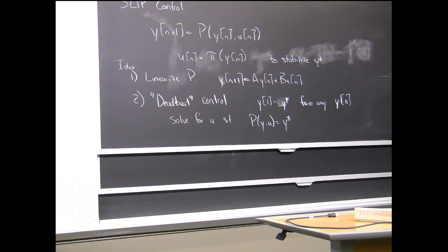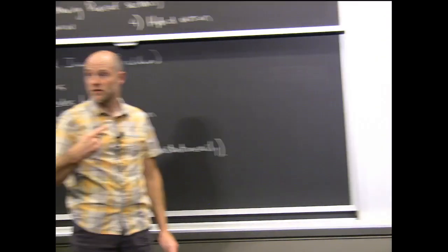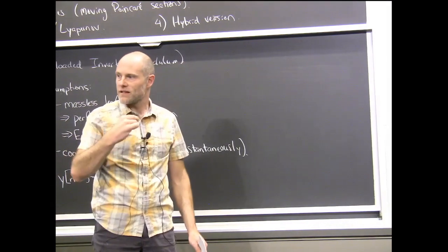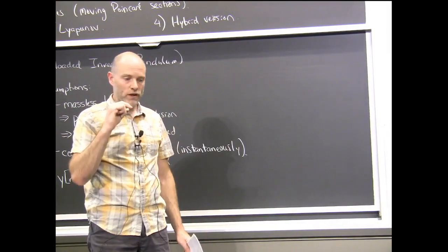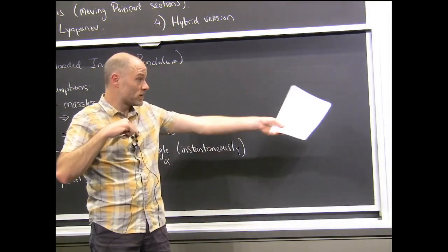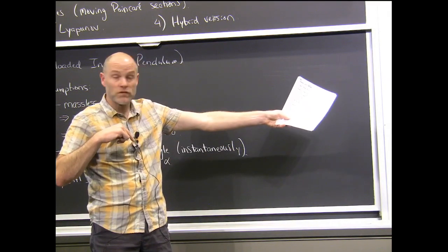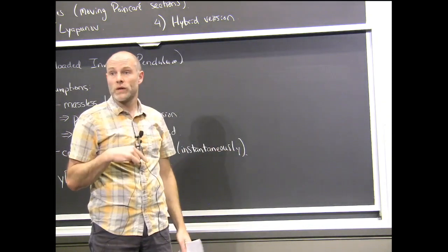Okay, so what does that mean? I'm hopping along, and I want to get to a new hopping height. I can choose a leg angle so that in exactly one step, I'm going to be at the new hopping height. That's a unique thing that we can do because we've gone to the discrete abstraction. We have time over the cycle to make that happen, but we can choose an angle, and using just analyzing the Poincare map like this, we can solve that problem.